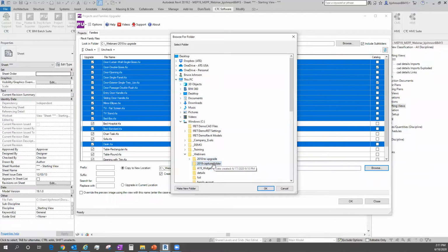And if you have to do an open and file save to a family, usually you'll see in the path that takes you to where it was last saved, even if it's been moved. So that would be one of those areas where you might have that instance where you truly do want to put them in the true final destination, and maybe just make that a hidden folder to everybody until you're done. So lots of ways to do it. I'm just trying to show it well and make sure you guys see what it actually does here.